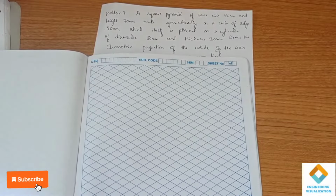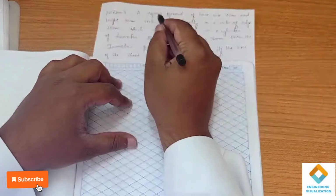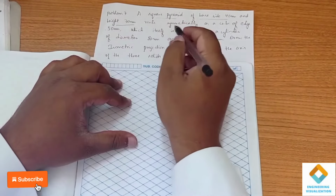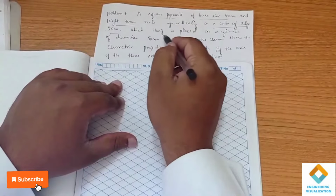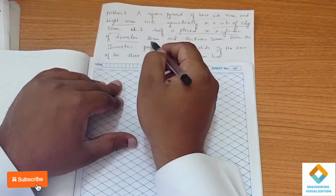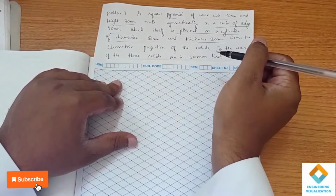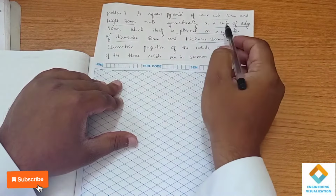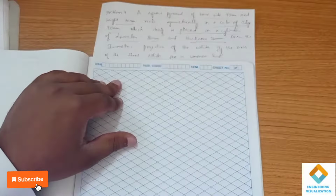Problem number 7 from isometric projection. You can see in this, a square pyramid of base 40 mm and height 70 rests symmetrically on a cube of edge 50, which itself is placed on a cylinder of diameter 80 and thickness 30. So here it is a combination of 3 solids. First one we have to do is the cylinder. Second the cube. Above it we have to place the square pyramid.